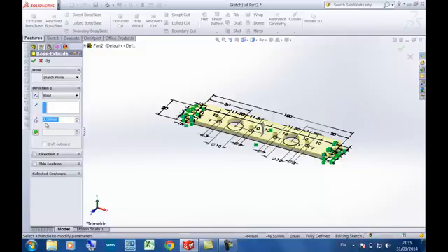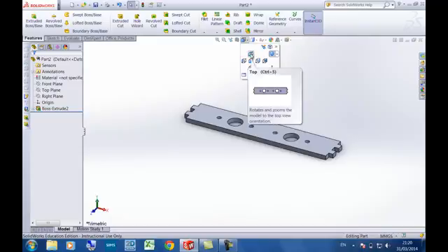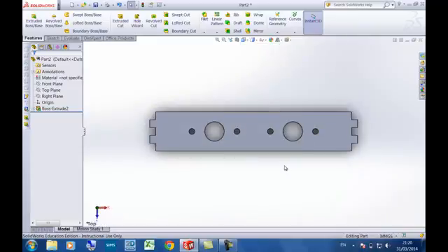By default, there should be something else, but since I used it before, it remembers the depth of my 3D model is 3 millimeters. So I'm just going to accept the 3 millimeter one. Now you can see my shape is beautifully cut out. I'm going to show a front view and top view. As you can see, that's like that.